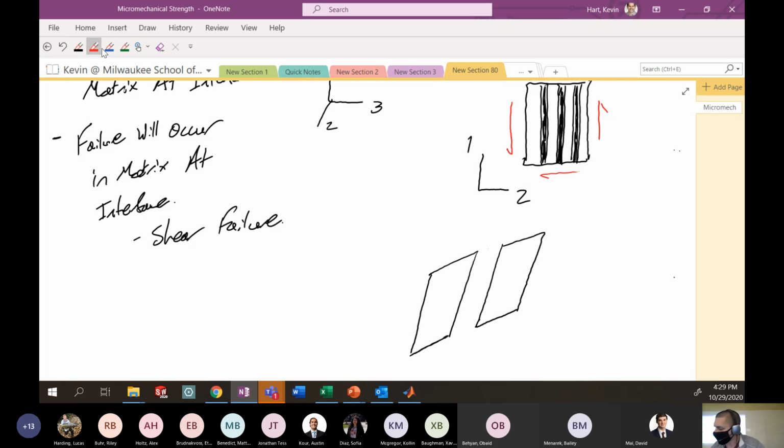And again, we've applied this sort of shear here on this guy. And we're failing right at the interface between what would be a fiber and the matrix right next to it. So usually the failure occurs like you'll see a clean fiber surface break. And then right here, this is the matrix that was attached to that fiber.